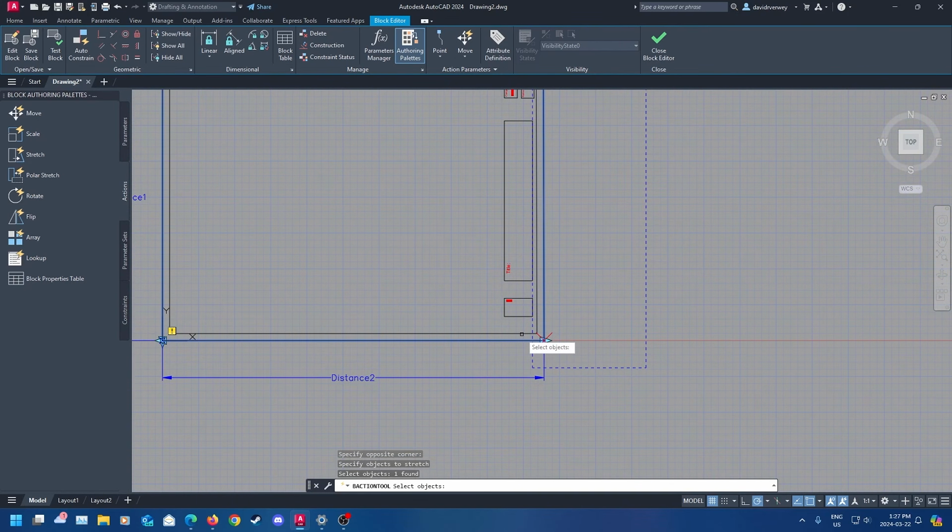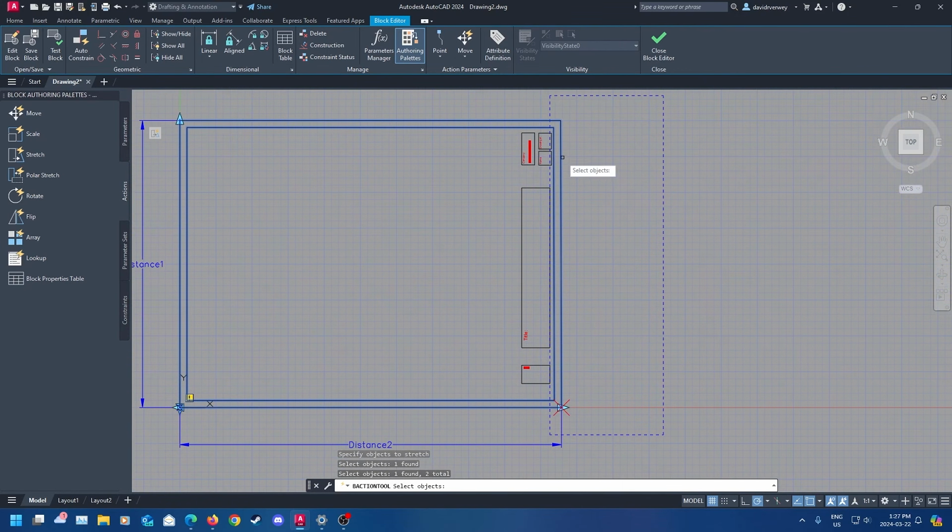We want to do just the frame in this case. For the other parts of this, so for the inner block parts, I'm going to make it so they scale. So then that way you can scale it and make it work. You can always move these things around when you're playing with your title block, as we've all found out. Or you can just get rid of them. Or you can also create an entire stretch command, which we will get into in a minute.